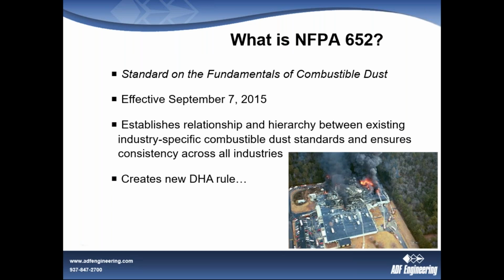So if you're not familiar with NFPA 652, this was a new standard that was issued by NFPA in September 2015, and it is meant to establish an overall hierarchy and to consolidate some of those rules that were inconsistent amongst all of the various industry-specific standards that were out there, such as NFPA 61 for the oil seeds and grain industries, or NFPA 654, NFPA 664, and so on, that covered different industries.